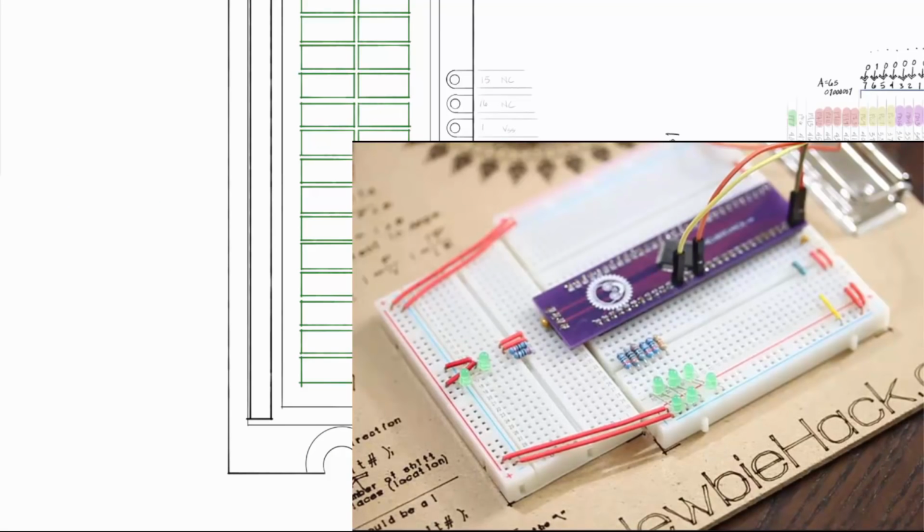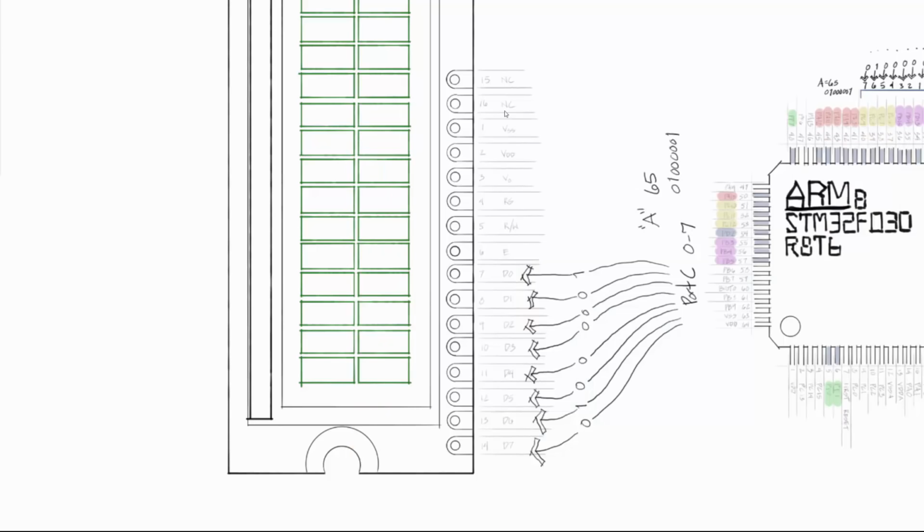And then when we get to the final step of putting the LCD on there, all we have to do is remove the LEDs, put the LCD inside, put the contrast and voltages and stuff like that on there, and test and see if it works. I plan on putting the LCD along this area here. The LCD has about 14 or 15 pins. I'm not sure if I have these actually as pins, but if I do, then I can just cut them off. Or I can just move some of the wires on the breadboard.